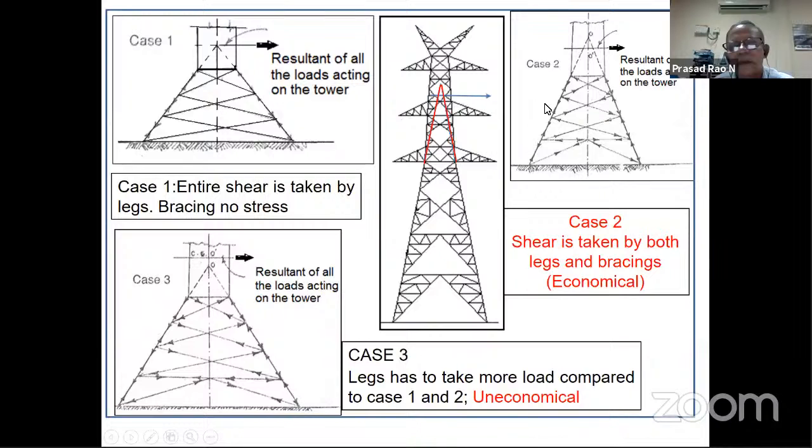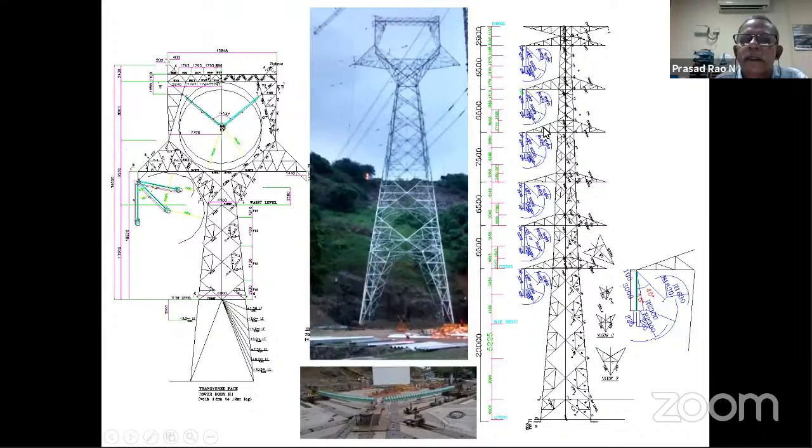It's a typical transmission tower and the ground clearances. Suppose we see here, the conductor will swing. In the midspan it will swing, and when it swings we have different types of vibrations, aeolian vibrations and other things. I am not going into that. This conductor should not touch the body of the tower. That is the idea. So the maximum swing angle will be taken from that, and clearances will be worked out.